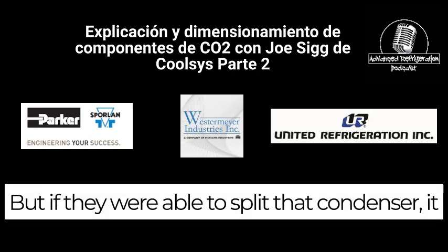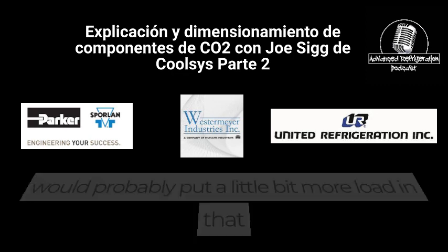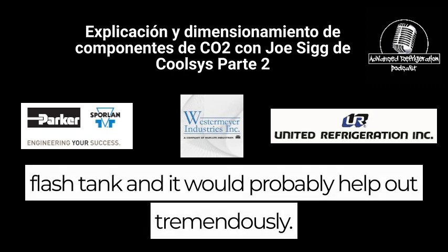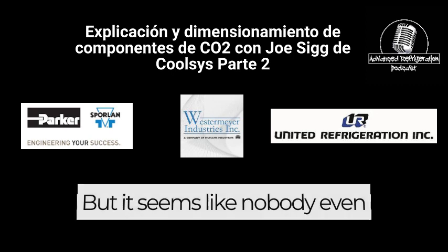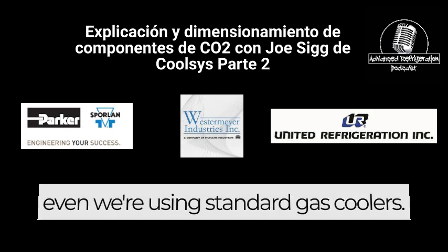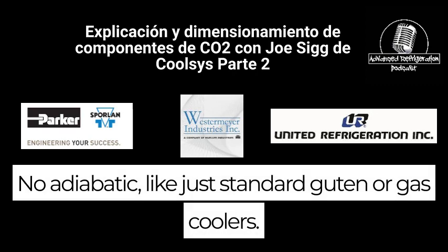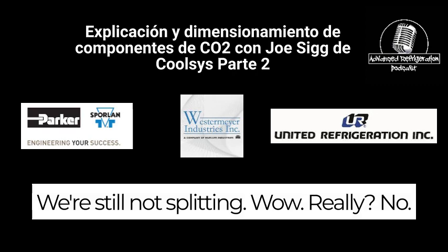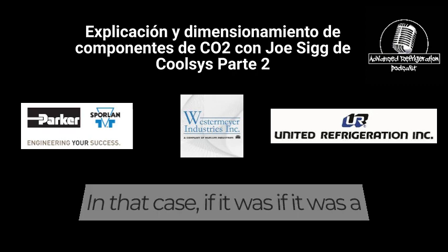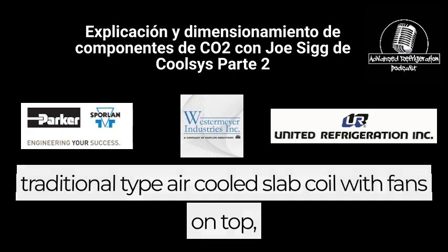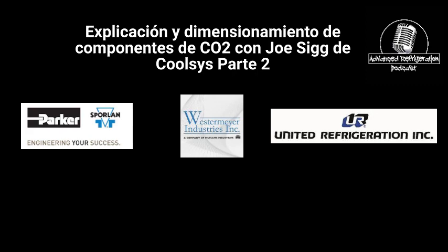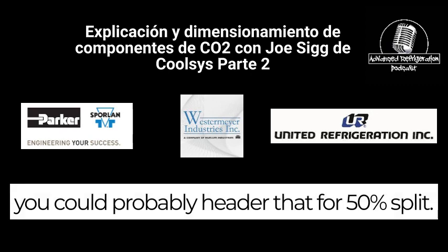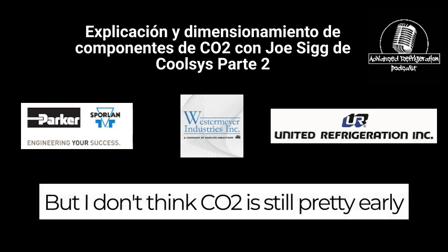But if they were able to split that condenser, it would probably put a little bit more load in that flash tank, and it would probably help out tremendously. But it seems like nobody is splitting, even when we're using standard gas coolers, no adiabatic, just standard gas coolers. Wow. Really? In that case, if it was a traditional air cooled slab coil with fans on top, you could probably header that for a 50% split, but I don't think